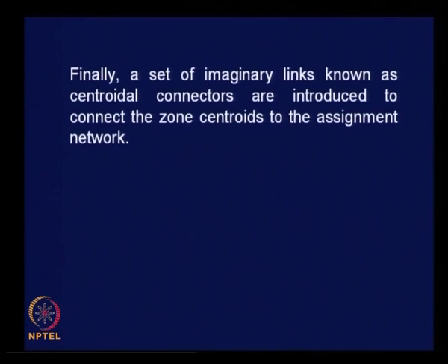And finally, a set of imaginary links known as centroidal connectors are introduced to connect the zone centroids to the assignment network. That is important. When we consider zone centroids as nodes, then these nodes are to be connected to the main network, otherwise we will not be able to analyze the traffic flow and assign traffic, right.